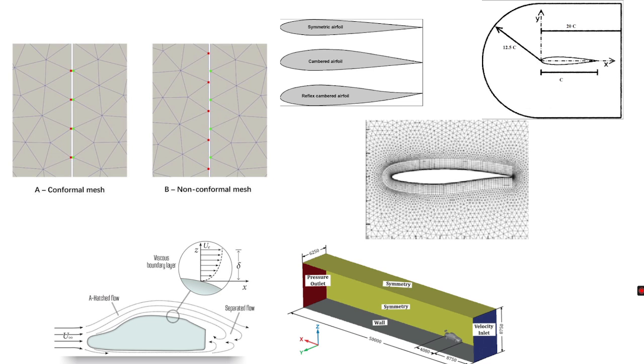Okay, so for internal flow, there is no need for defining this type of external domain like we define in external flow. Internal domain means the internal area itself is the domain. So we simply discretize, or give the meshing to, the internal flow, and we can go for the next stage. So meshing: after creating the model and defining it accurately, we can go for the meshing. Generate the mesh for the computational domain.